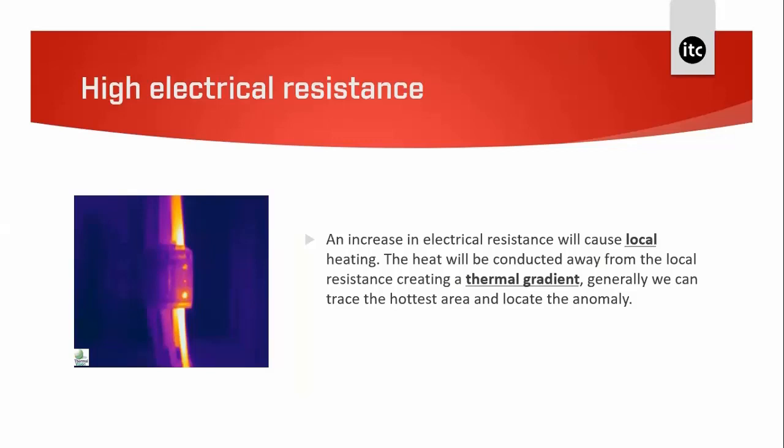With the hottest area at the high resistance, it should be pointed out that the resistance itself can be quite low, but will be higher than other good parts of the circuit. So by high resistance, we are speaking comparatively. The temperature of the connection will be related to the electrical load on the circuit, and if the current suddenly increases, then so will the temperature. So surveys should be undertaken under normal operation conditions if possible.